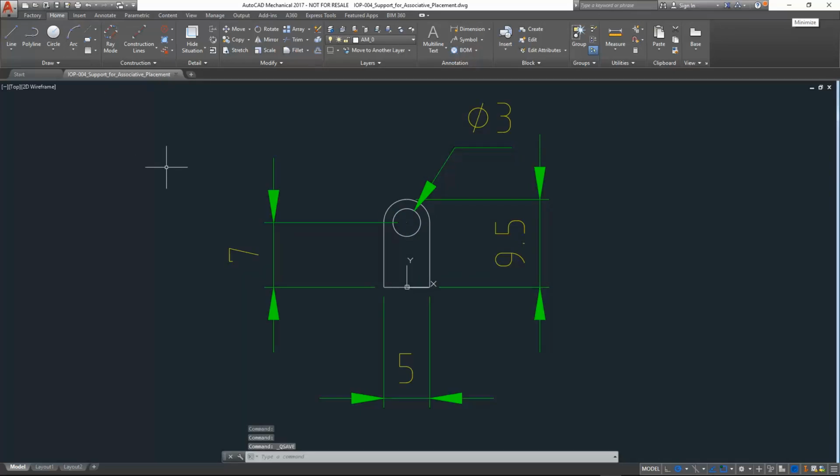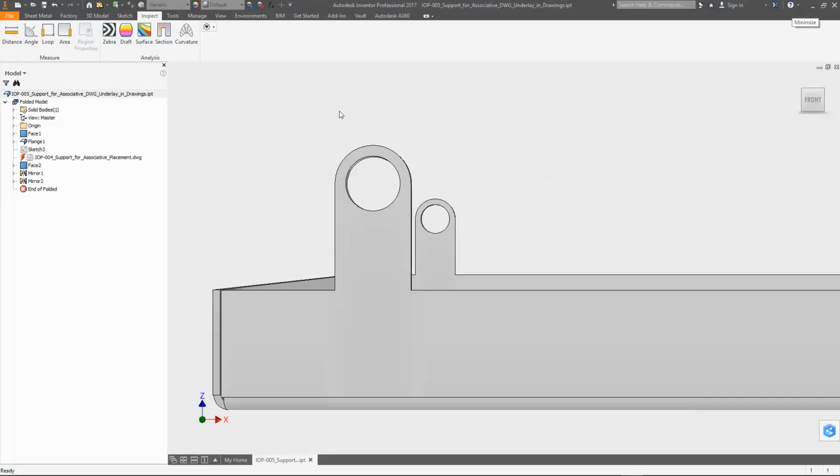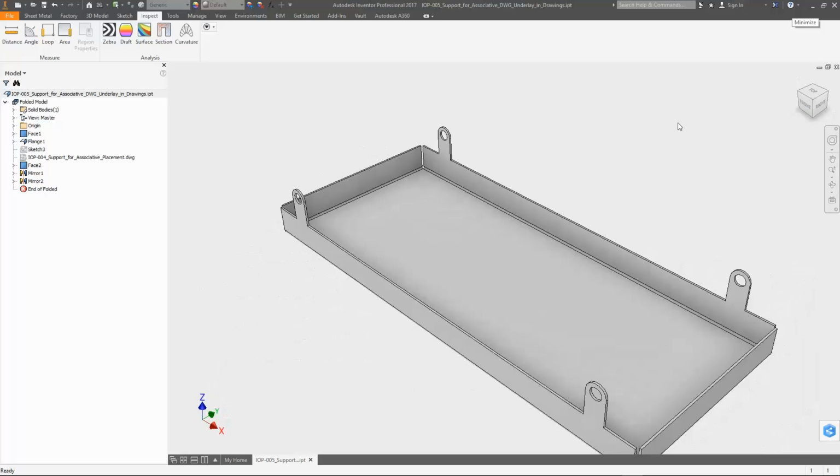Don't forget to save and switch back to Inventor again. Once a geometry update is outstanding, the local update command is active. Click on it and you get the latest geometry updates. I hope you could already see the hole got a bit smaller. Nevertheless, we measure the diameter again to double check if we got the correct value. Yes, 3 mm in diameter like in the DWG file.